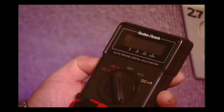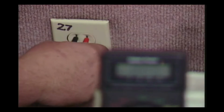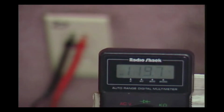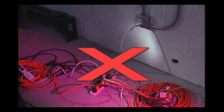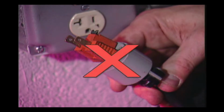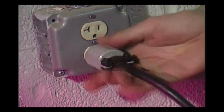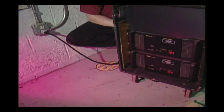You should always check the outlets you plan to use for the system. Purchase a multimeter, which you can use to test AC outlets for correct voltage output as well as cable continuity. If a fault is detected, the outlet should not be used. Try to spread your power among several outlets on the same circuit instead of overloading one outlet box. If you're experiencing ground loops, never use an AC ground lift like this to lift the entire system. Instead, use balanced lines and cables with 3-prong AC plugs without adapters, and interrupt any ground loops at the line level shield grounds, which we'll talk more about in a moment.